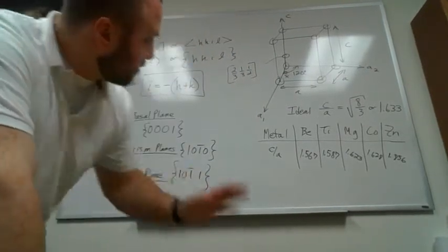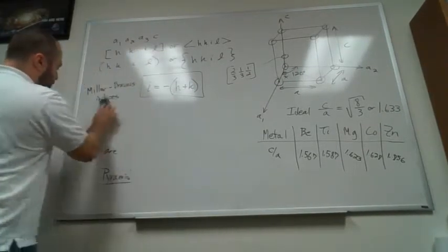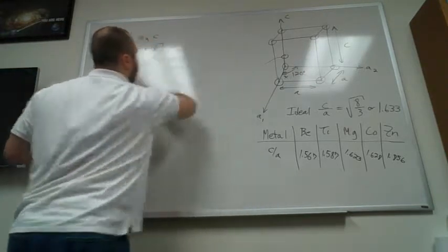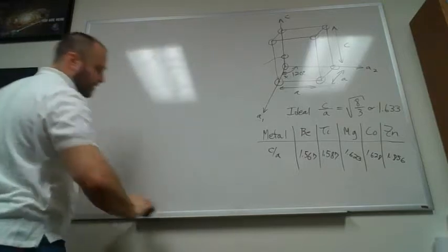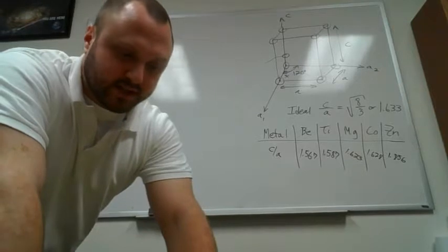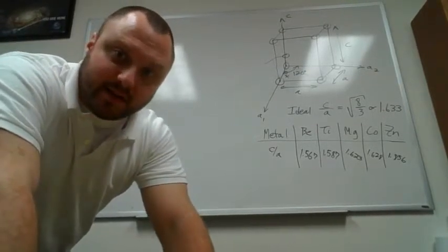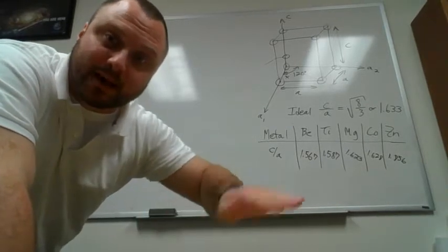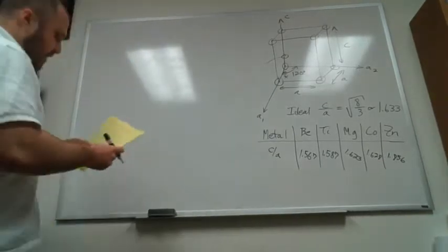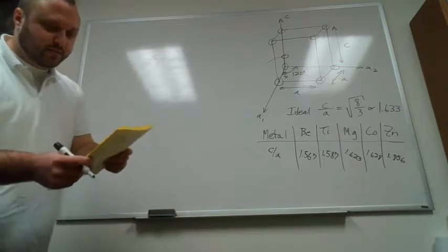So when we want to start looking at this microstructure, we care about what happens with dislocations and plasticity, like everything else in this class. So we can go and ask the same question that we saw for FCC materials and say, okay, where would they be? Okay, and our answer is going to be the same thing. It's going to be that they're in the closest packed planes in the close packed directions, okay? These are going to be really the same thing we saw in FCC. We're just going to have that slightly different notation, okay?